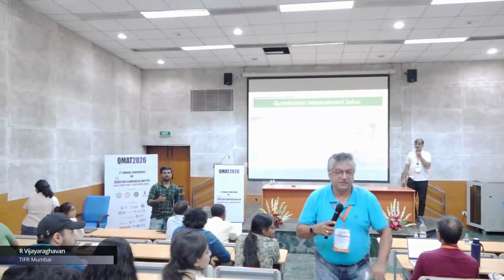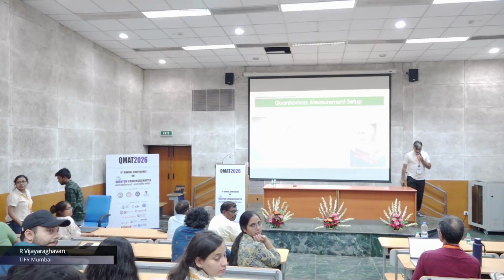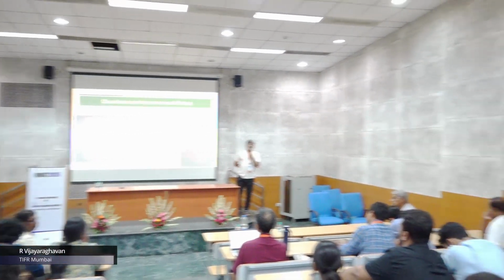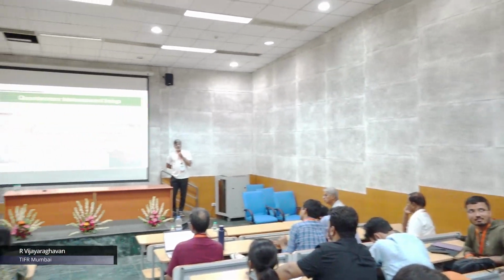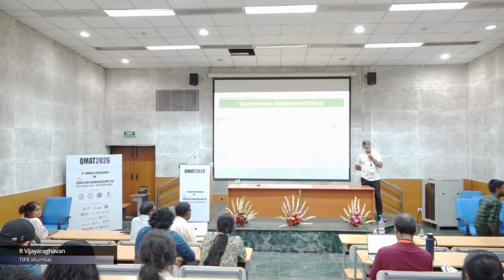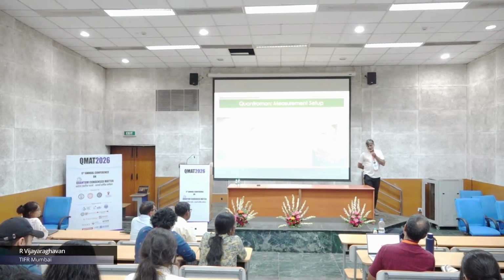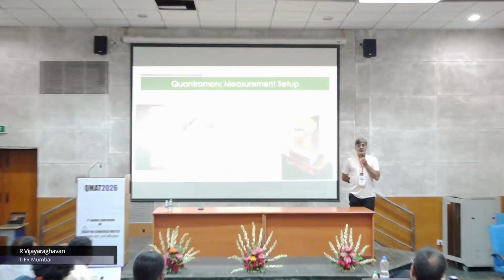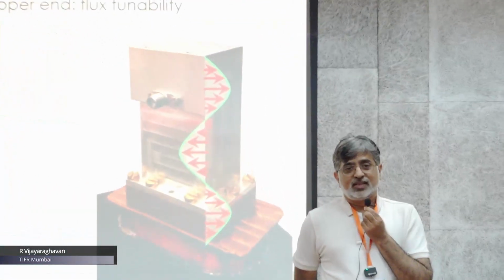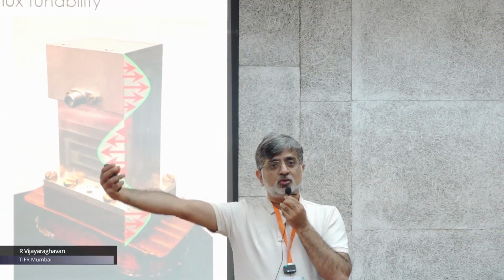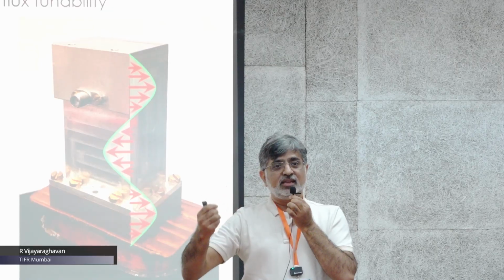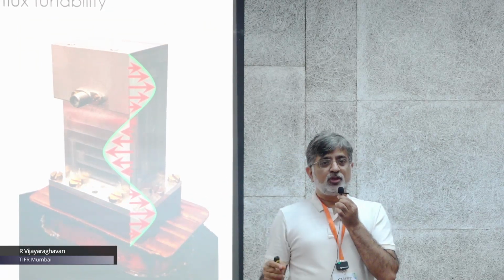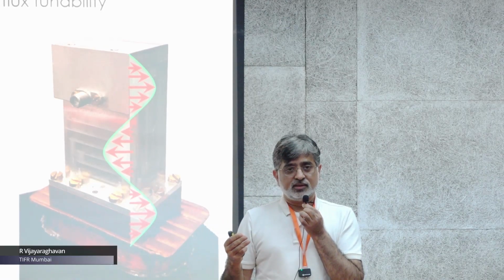Okay, last question by Anjan. I was curious, this decoherence time, is it extrinsic or are there intrinsic factors also? They are both. If you have done your job correctly in terms of your design, you will suppress all the extrinsic factors. So, for example, because the cavity has to be coupled to a microwave feed line, that can give rise to dissipation. But if you design the frequencies and the coupling carefully, you can make that number insignificant.